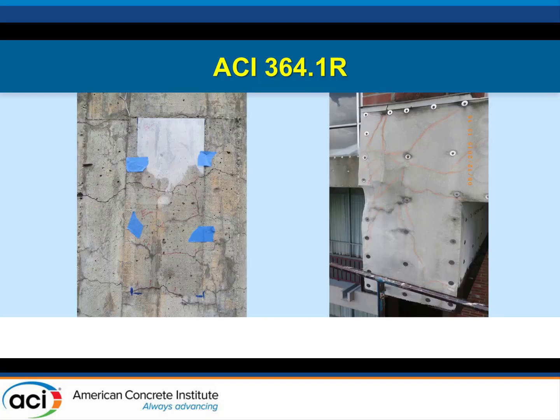So on the left-hand side, you see what the AAR looks like up close. You can see the cracking and fragmentation that's happening in the concrete. We've gone around the outside and installed screen and netting. It's shown on the right-hand side. It really had two functions. It certainly kept the fragments of concrete from coming off the face of the building. It actually did a pretty good job of concealing it. So when you walked up to the building, you didn't necessarily notice it.